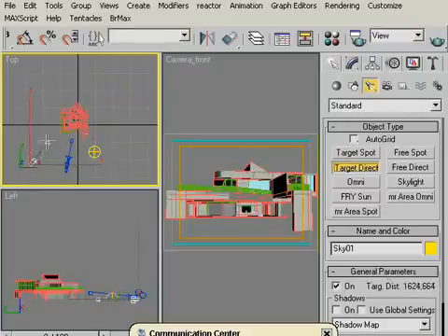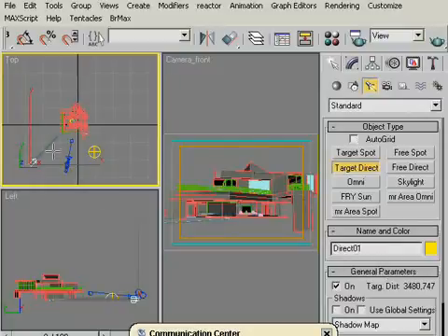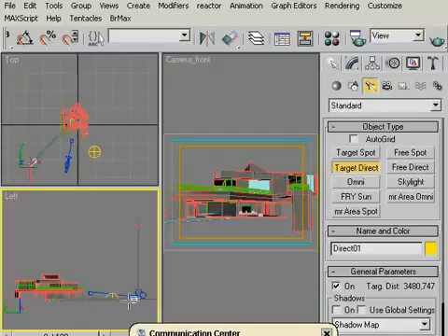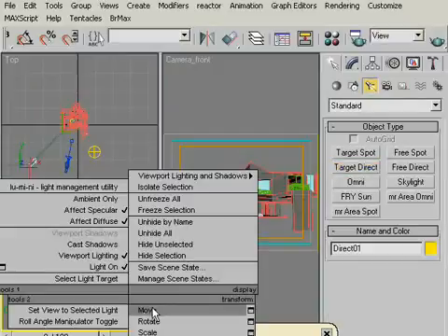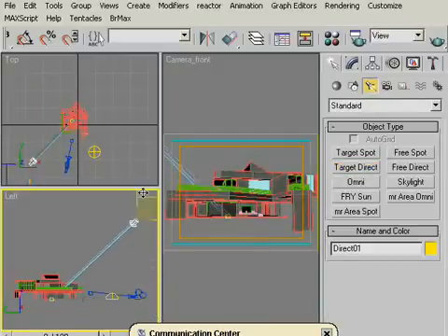left bottom side of our plane and drag it till the middle of our architectural model. And at the left view, move our directional light much higher somewhere here. That's good. This will be our sunlight.